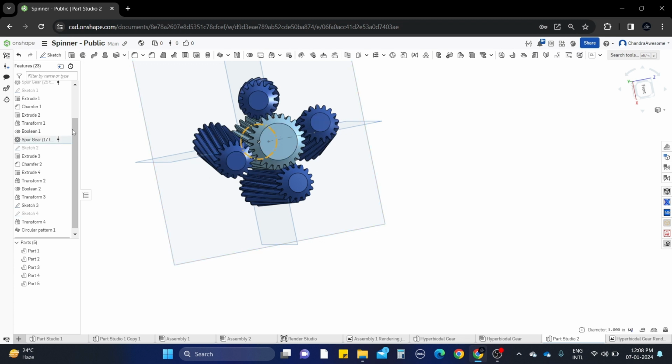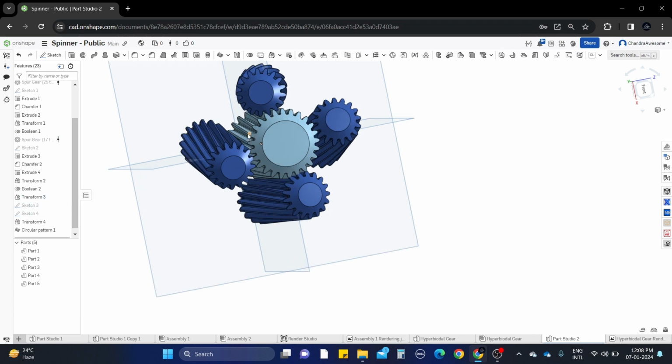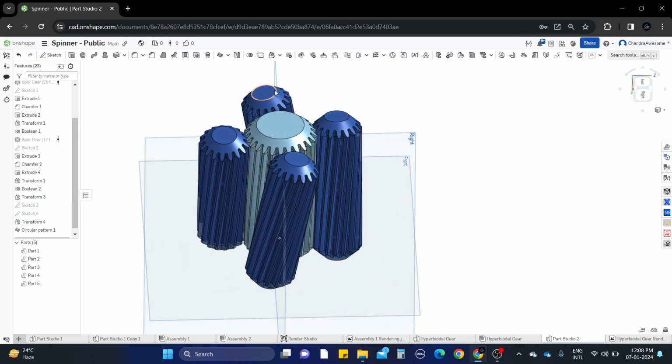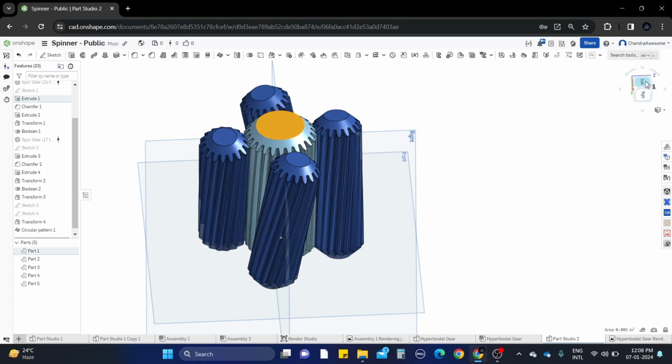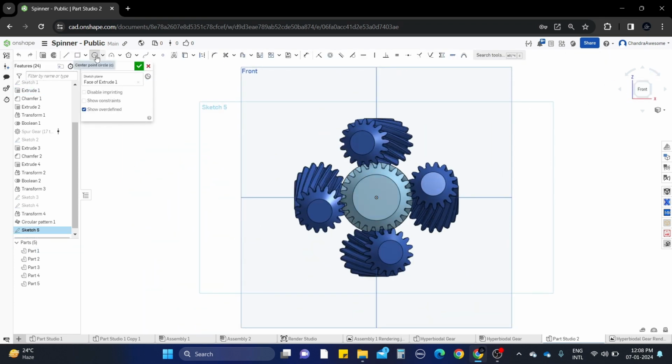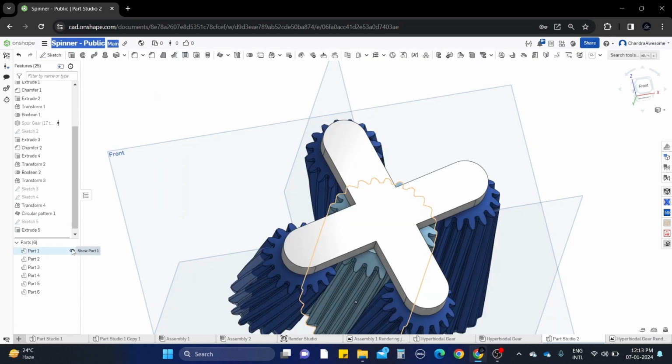Now add the sketch as shown on the center gear to add the frame for the gears to hold them at their position. Now draw the circle and also the position of the gears using the Use tool and the Slot tool for a simple drawing frame. This is the final frame. You can also add your own frame design just to hold the gears.